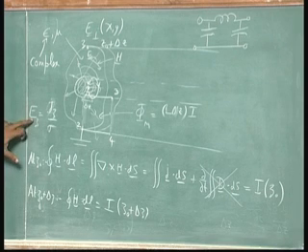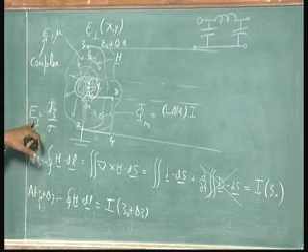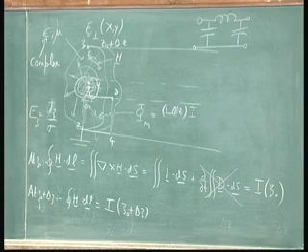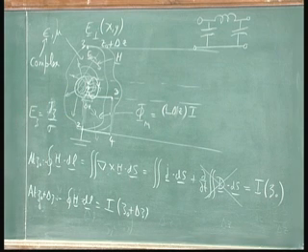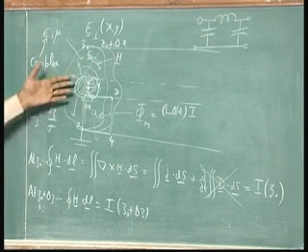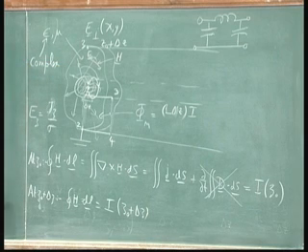But this is violating whatever we said about these waves. These waves have only x and y direction, but we require a z direction electric field. So it means that a true TEM wave is not possible the moment your wire has finite conductivity. If it is a superconductor we can manage, but if it is not a superconductor then we can't have such an electric field.